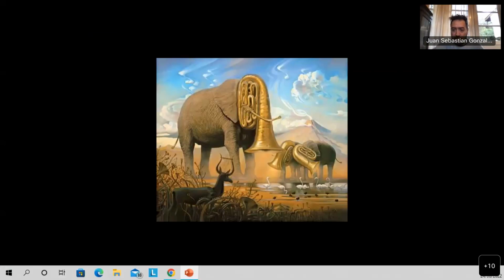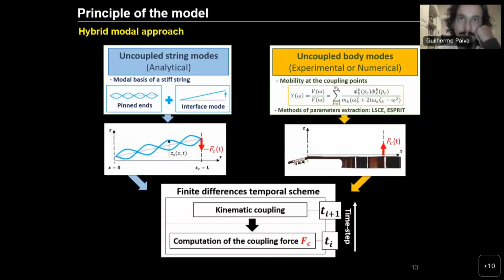David asked for variations in the damping of the wood. And actually, what model are you using for the damping? I was expecting this question. Our model considers the real body modes; we assume that the modes are real. So we are performing an undamped modal analysis.